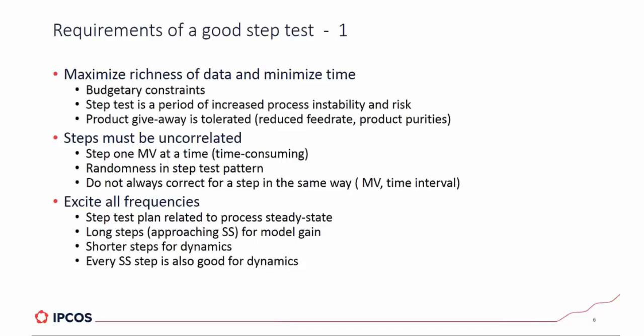There is a limited amount of time that we can spend on the step test, not only because time is money, but also because a step test is a period of increased instability and risk on the plant. While we are doing our step test, it's basically an operation that is not normal to the operator, and they would usually prefer us to come and do our thing and get out of there as quick as possible.